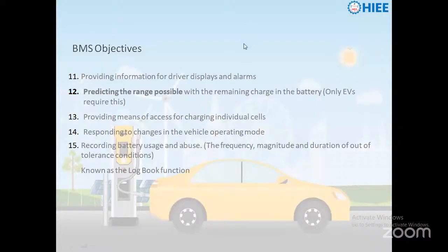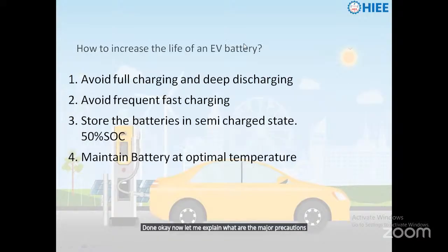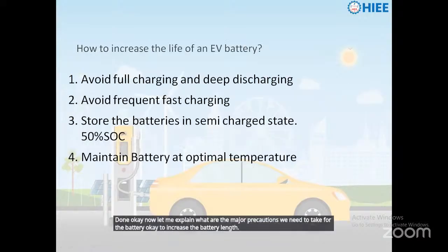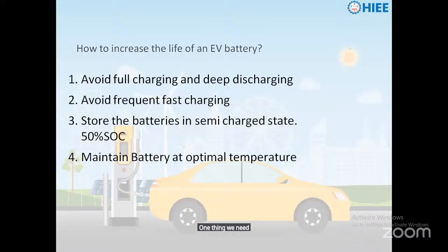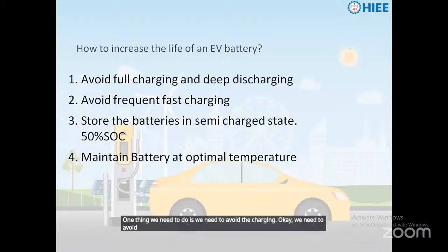Done. Okay, now let me explain what are the major precautions we need to take for the battery to increase the battery life. One thing we need to do is avoid fully charging and deep discharging, as we discussed. Then we need to avoid frequent fast charging.